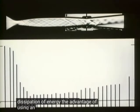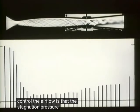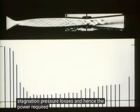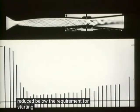The advantage of using an adjustable second throat to control the airflow is that the stagnation pressure losses, and hence the power required to run the channel, can be reduced below the requirement for starting.